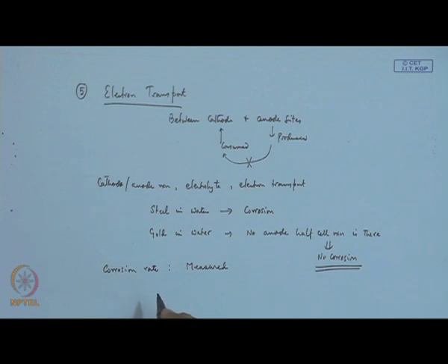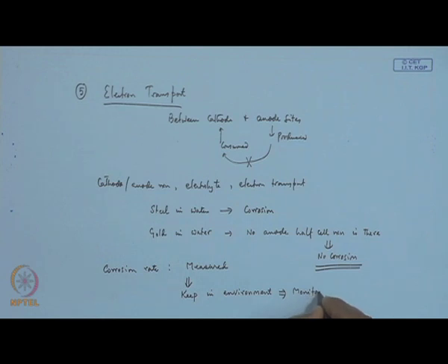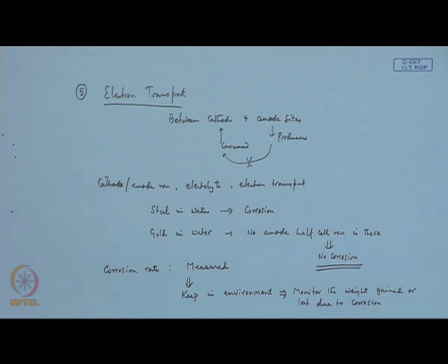Maybe in a very simple way, you put the material which is going to be corroded in the environmental condition, keep it in the environment, and then monitor the weight gained or lost due to corrosion.